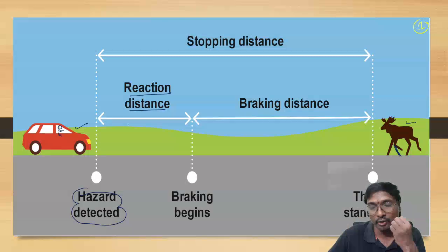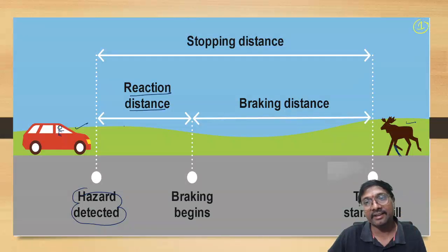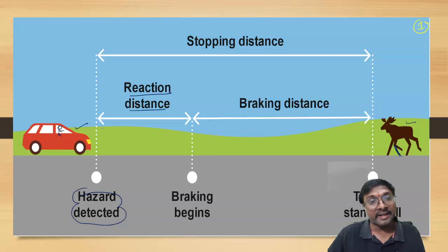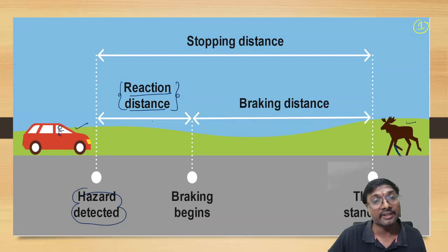Perception: observing the information of this object, analyzing that, recollecting previous similar situations; that is interaction time. Next, based on that you will feel some emotion, like fear, that it will be dangerous if you go and hit that object. Based on this emotion we take a decision, that is the application of brakes. That is volition time. The distance traveled during the time your mind takes for the entire PIEV process is your reaction distance or lag distance.